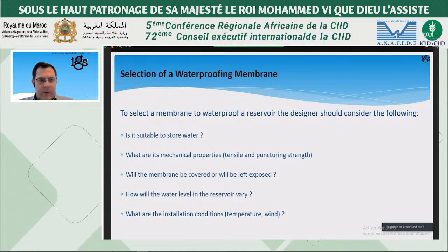Also, you need to consider what mechanical properties are required, especially tensile strength and puncture resistance. Will the membrane be covered or left exposed? Sometimes it's questionable, and for other projects not at all, because of UV resistance or problems with debris in the water.